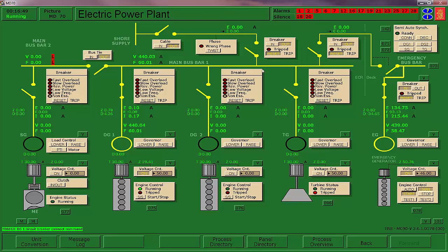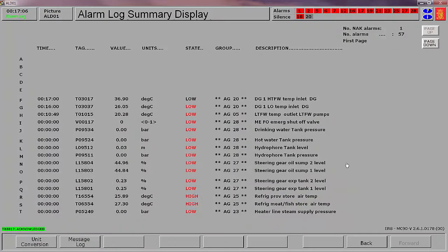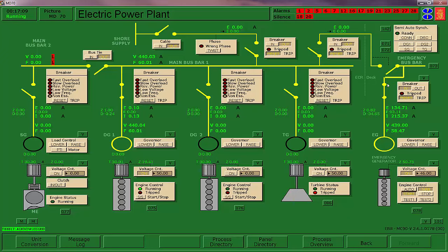And I'm going to switch over power to the emergency switchboard. Watch when I close this tiebreaker on the main switchboard. You'll first see this disconnect breaker open and power is lost on the emergency. Then the jacket water low temp alarm, and your pumps will drop off. So this disconnect breaker opens, and then the emergency bus tie will close. Watch it happen. Okay, that opened and then that closed. All right. So we've lost power on our pumps.